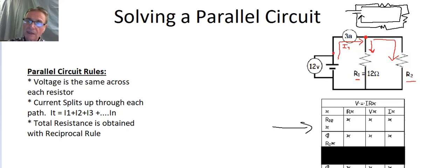Notice, if you will, in our parallel circuit, we have 12 volts across our battery, which means that essentially I've got 12 volts up here and I've got 0 volts down here. So if I do the same thing that I did with the series circuit, I trace a line so it goes up along here and it goes up along here. I'm not going through any components. So when I get to this point here, if I had 12 volts originally right there, and I've only simply gone through a wire, and this 3 amps here, that's just indicating what my total current is, that's not a device there. And I get to this junction point right here, what's the voltage that I've got right there? Well, it stays at 12 volts, right? So I've still got 12 volts there.